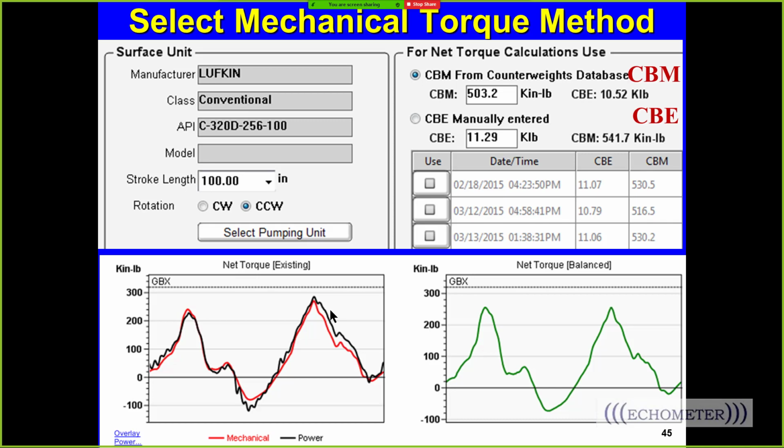Yeah, and I'm not sure you really want to use amps when your gearbox loading is close to the gearbox rating, because if you use amps and your gearbox is still overloaded, then you're going to spend a bunch of money for a damaged gearbox. I've been in meetings where gearbox failure was a problem, and they were using the amp method and having lots of failures.